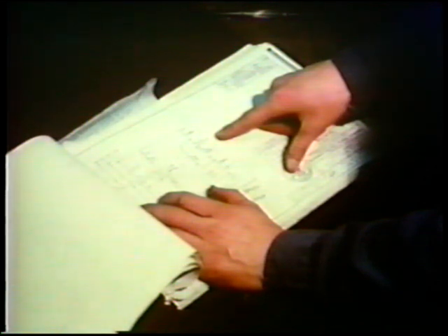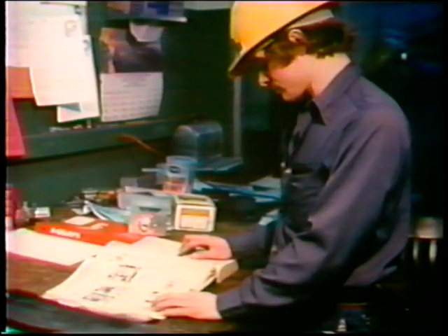From the schematic, you can trace the current flow to find out the controller's normal operation. Your plant might have a system description or a technical manual that will provide you with information on the controller's normal operation. But no matter what source of information you choose to use, if you know how the controller is supposed to operate, it'll make it a lot easier to identify the symptoms of a problem.